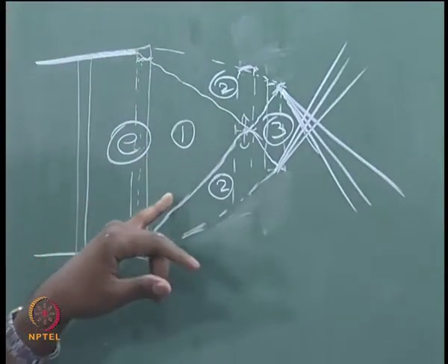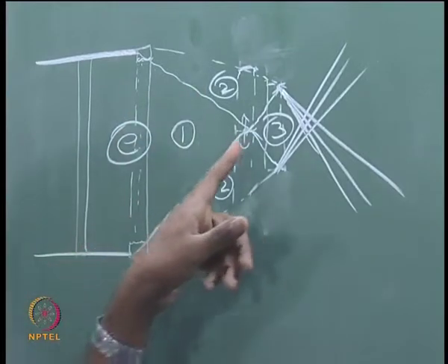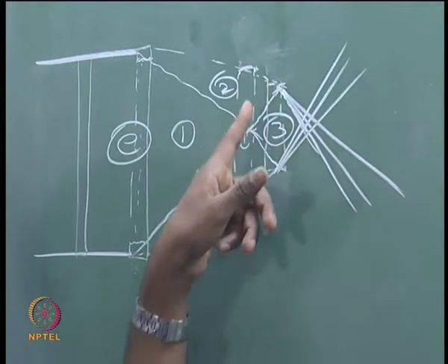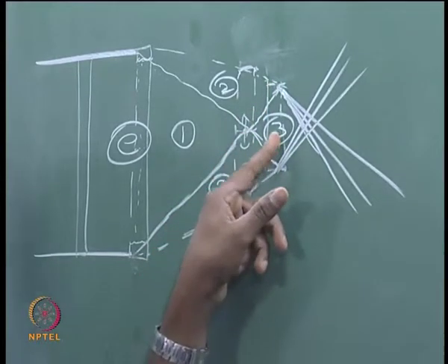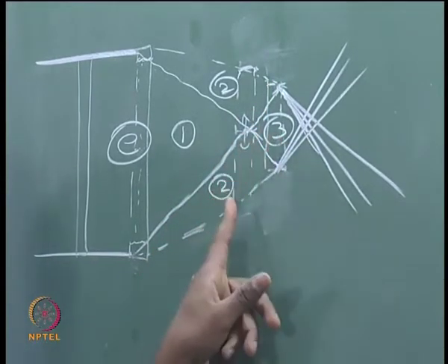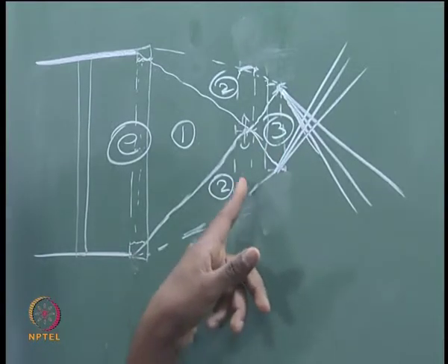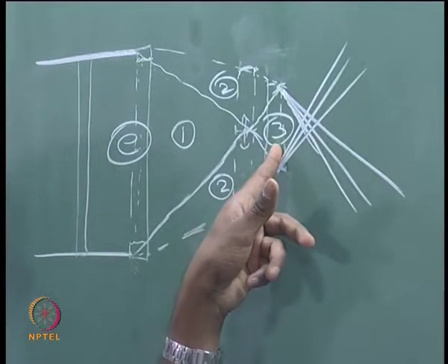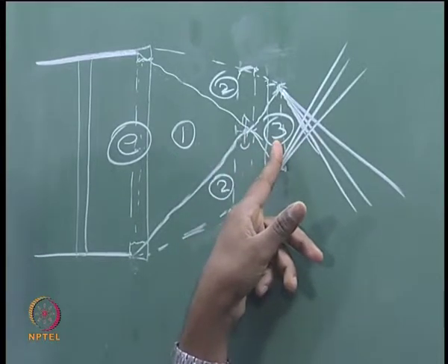Same thing this side, same equivalent shock here, and then because the shock is continuously going past that point, the pressure increased from 2 to 3. 3 is above the back pressure, because atmospheric pressure gas is processed by a shock.